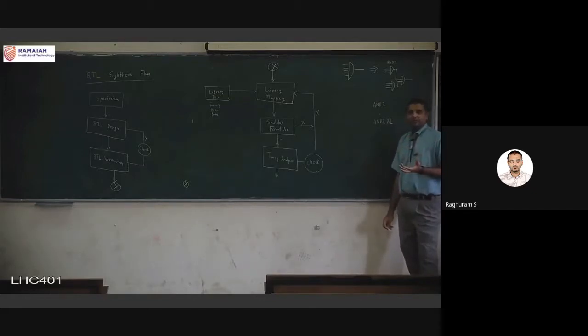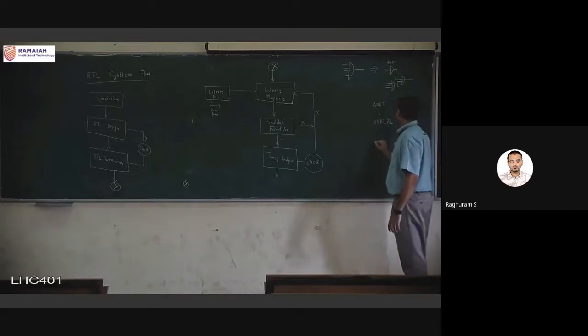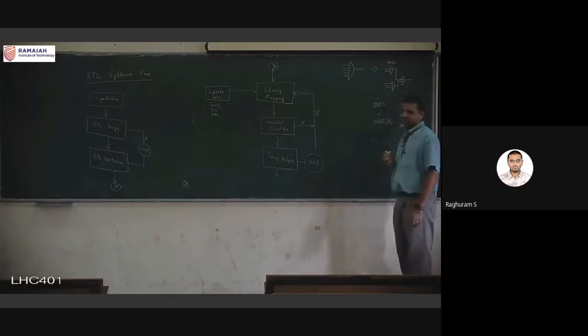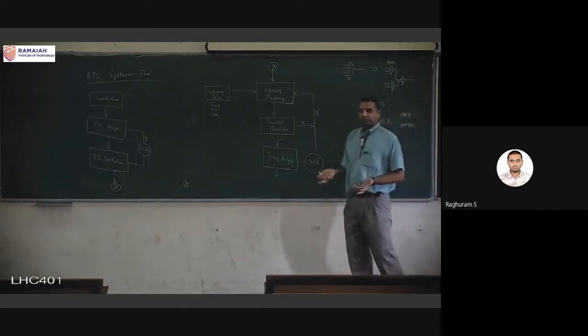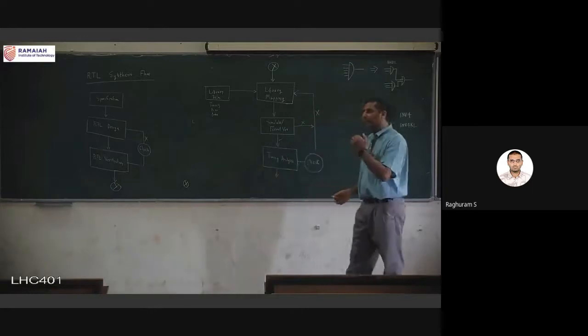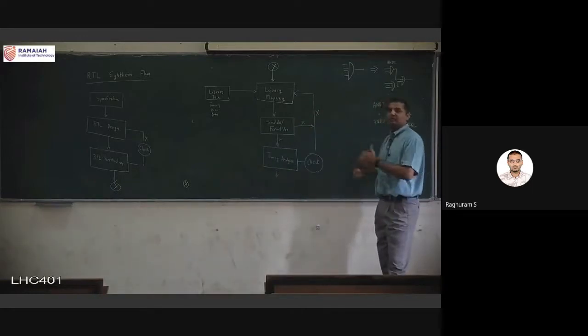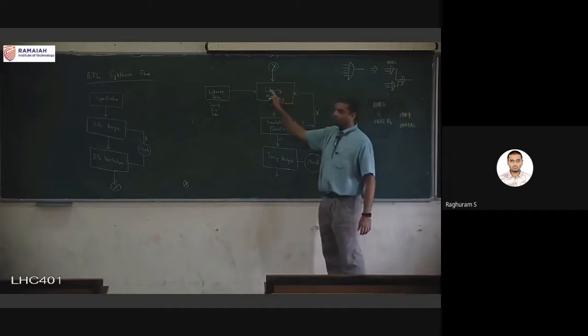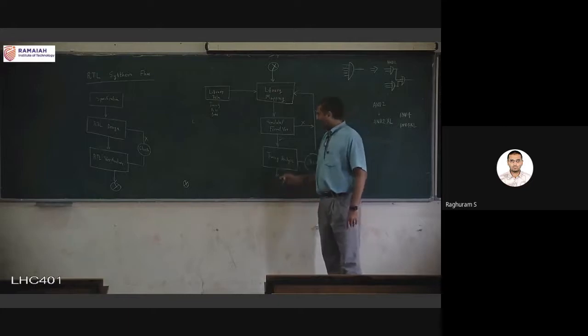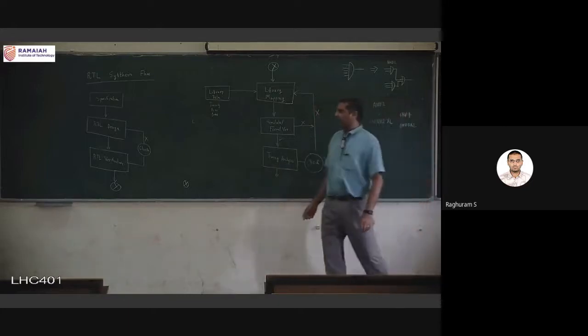Of course, after a certain point, if you're not able to do it, for example, it might go all the way up to inverters, for example, inverter 4, inverter 4XL, etc. Many are there, but at a certain point, it might fail. Of course, there's always this thing that timing might not be satisfied, but we cannot do anything about that. But there are multiple cells for each functionality, and it will try. If it is satisfied, it will go. Otherwise, it will redo the mapping with a new cell, and it will try to satisfy the timing. So once the timing analysis is done in this step,